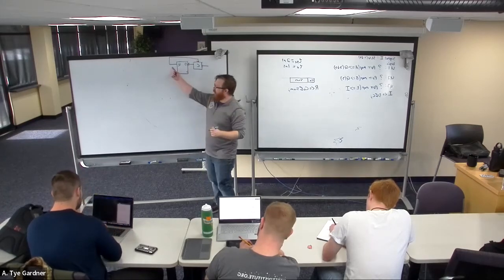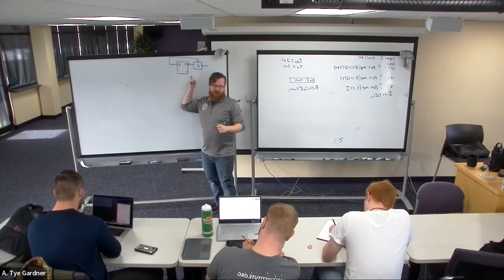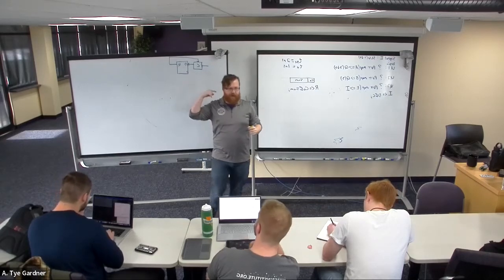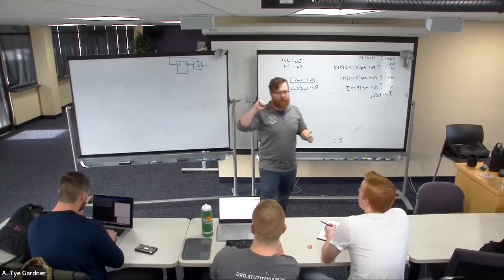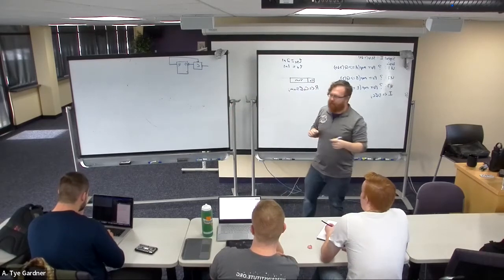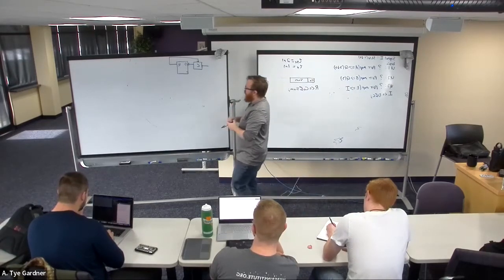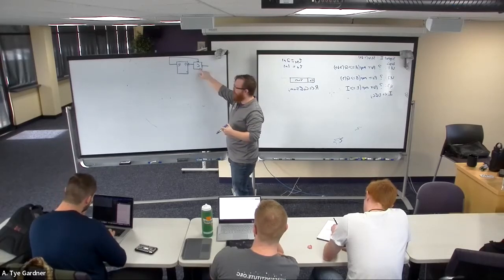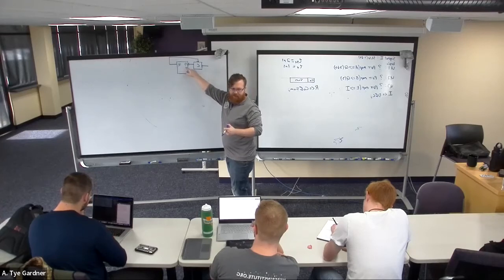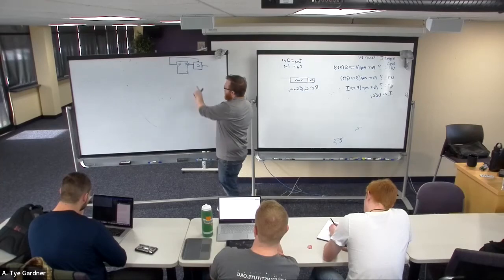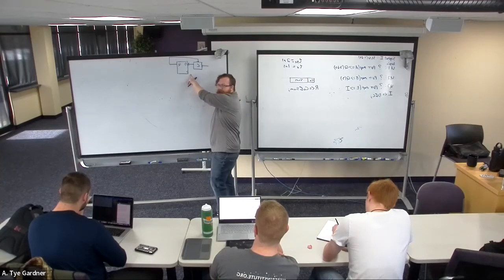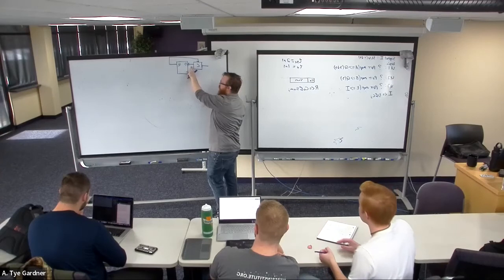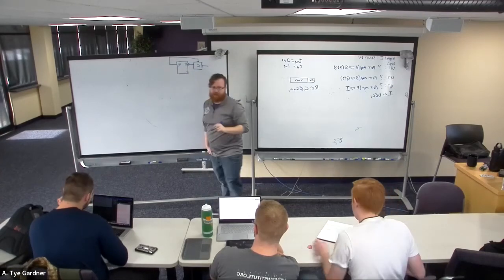So when we send the output back as an input, we call this feedback. There's a whole bunch of math, and a big reason that you take all the math you do is to understand the math of feedback, which you'll get to in later classes. That's what it is. So this is feedback. It's sending it back to some combinational circuit that is going to help the next round make a decision. Okay. So there's an issue, which is that there's a clock here, right? That is taking whatever is on C and updating it to Q.